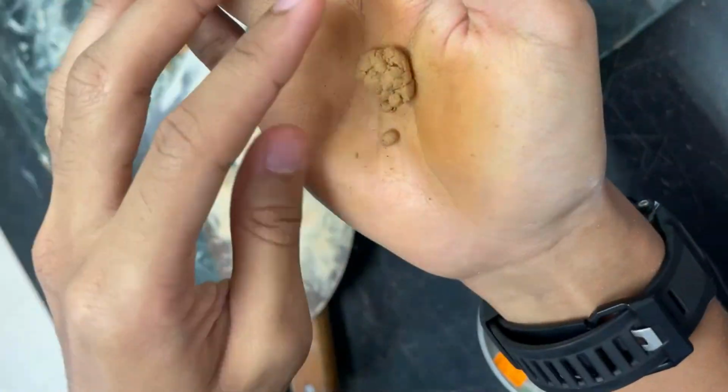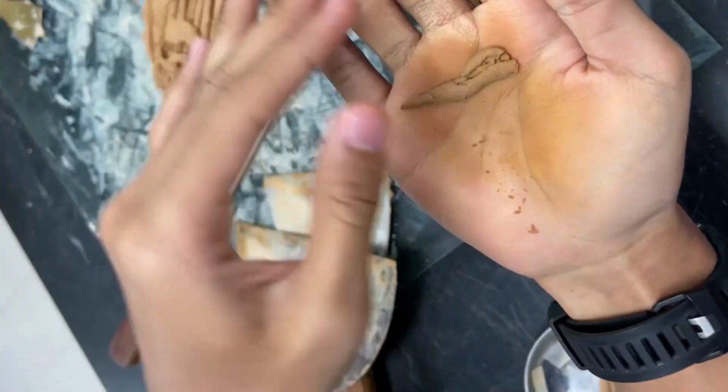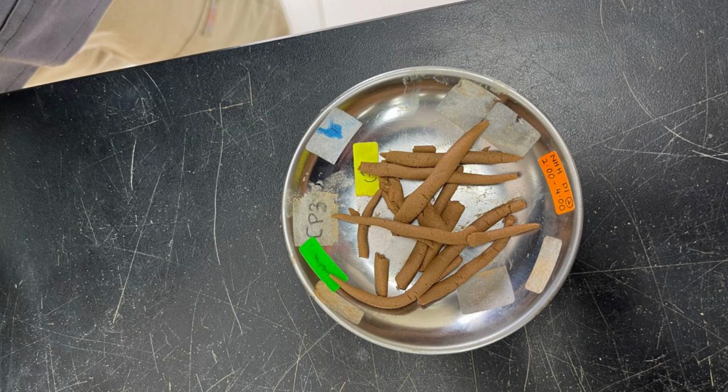parts. The pieces are kneaded and reformed into an ellipsoidal mass and re-rolled. The step continues until the soil can no longer be rolled into a 3 mm diameter thread. The portion of the crumbled thread was gathered together and placed into a moisture can. The mass of the moisture can that contains the soil was weighed and recorded.